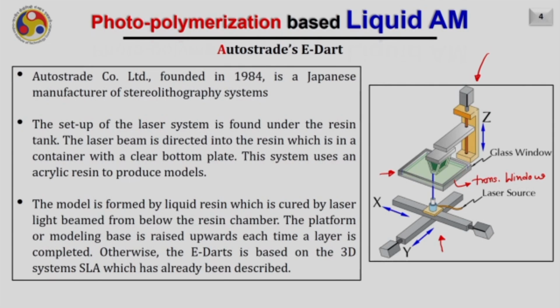So, here why is it flying optics? Because this is the optics, right? And it is attached on an x-axis, and also this x-axis is attached on a y-axis through the corresponding motor. Assume that this motor corresponds to the y-axis and this motor corresponds to the x-axis. When these motors rotate, this optics will also move. Therefore, we are calling it flying optics because the optics is moving.